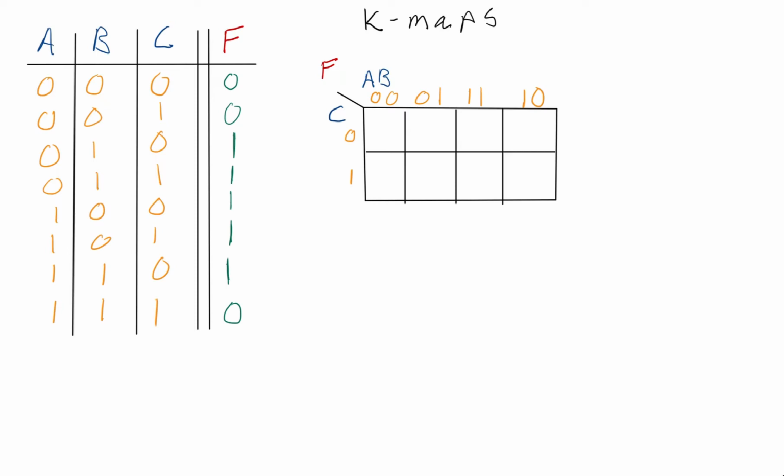So by minimizing the number of gates that we use, we are able to make smaller chips. They're cheaper to make, they use less electricity, and they're faster. So it's really important to minimize the use of gates. K-maps is one of several ways that you can create a minimal Boolean algebra expression that correctly gets the right output but uses the fewest number of operations or gates.